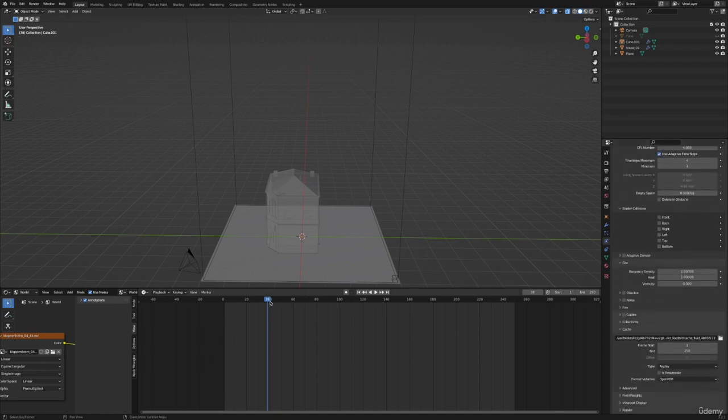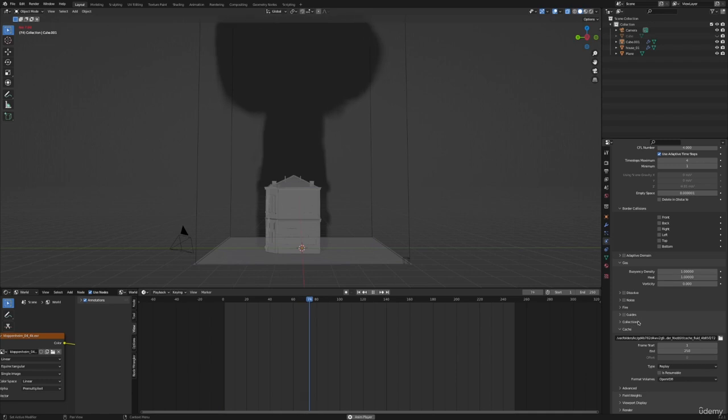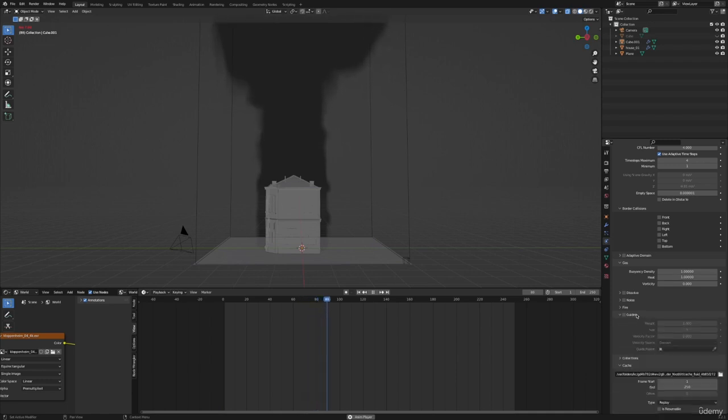Now, to set the way the gas moves, here we have our gas option. We have 3 sliders here now, and the first one is buoyancy density to control the fullness of the gas, so to speak. Then we have the vorticity, which basically means how you measure how turbulent your gas is calculated, so to speak. Basically how turbulent our gas behaves. This is just known as vortex strength, so you can play around with these values and find your own personal optimum. Unfortunately, there's no presets here once again, which means that if you like it, you can write down your own values and make your own presets, but we basically start the simulation on the standard setting.